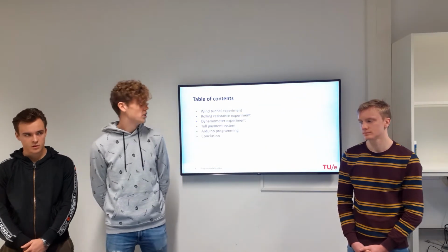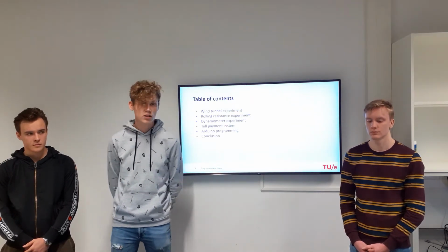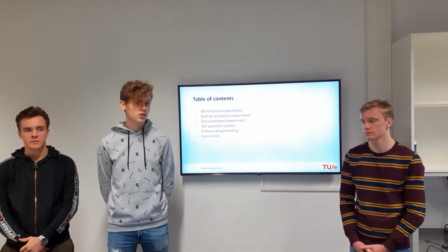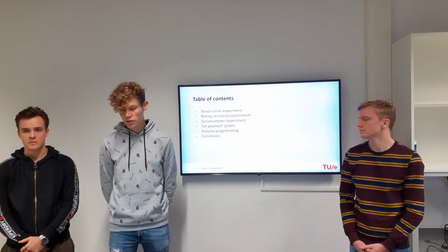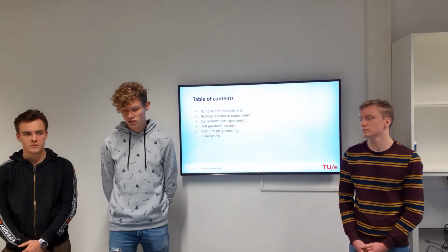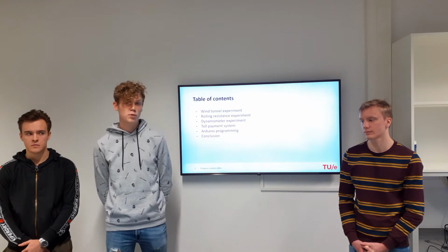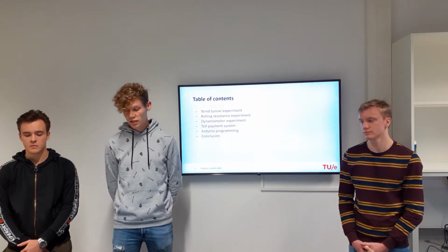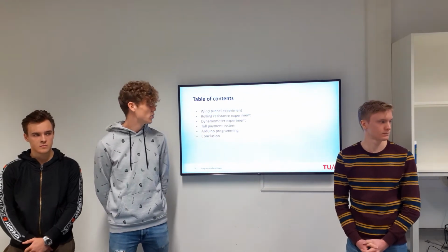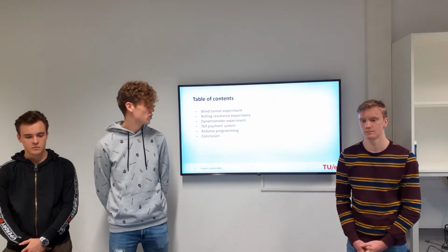We're going to talk in this presentation about a few things that we're experimenting on and working on in this project. We have 3 experiments. The first experiment is the wind tunnel experiment. This is to determine the air drag coefficient of the car, and we're going to do several iterations, with and without modifications to the car. Our second experiment is the rolling resistance experiment. This is to determine the rolling resistance coefficient and to see if we can work around certain resisting forces to have as efficient a car as possible.